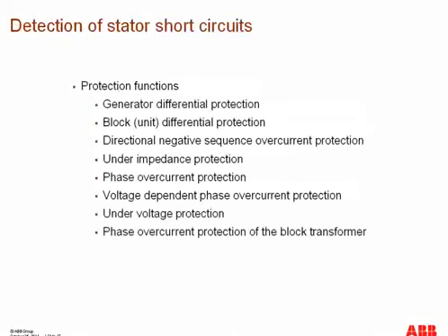In addition to differential protection, we can have directional negative sequence overcurrent protection, impedance protection, phase overcurrent protection, and other types of protections as well, like voltage dependent phase overcurrent and phase overcurrent protection of the block transformer. So there are several ways to detect and eliminate the stator short circuits.